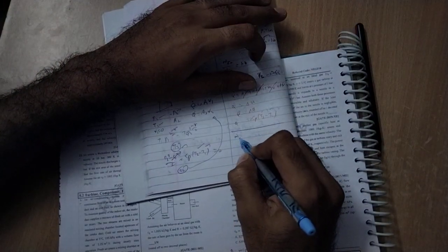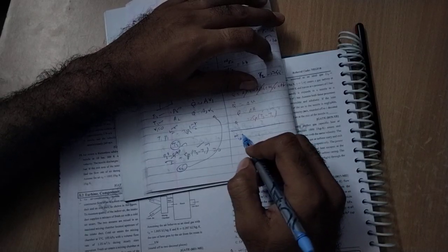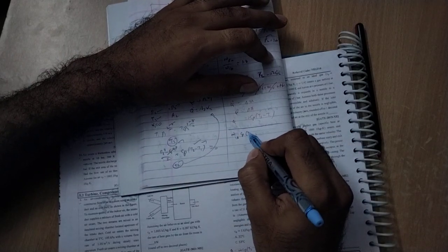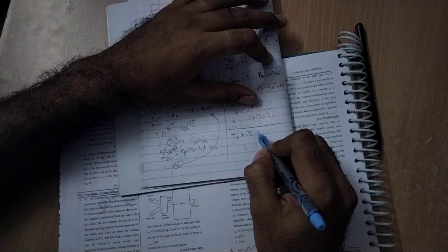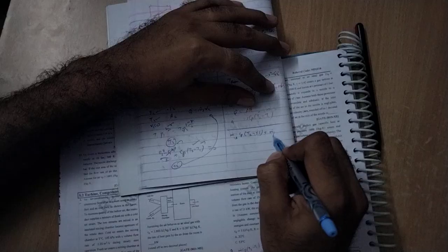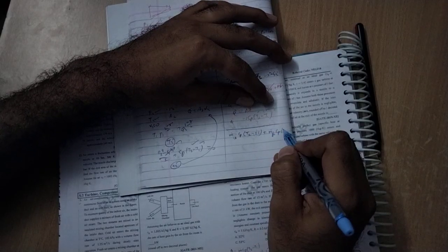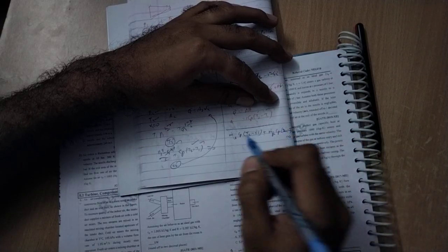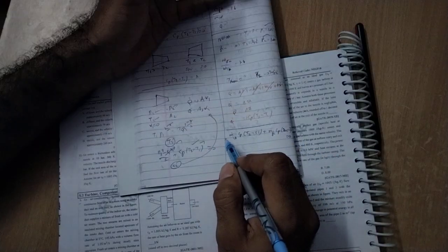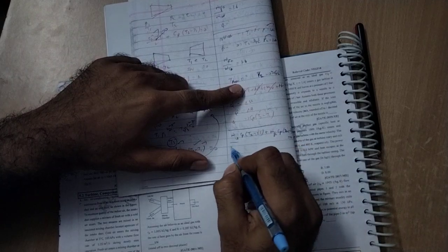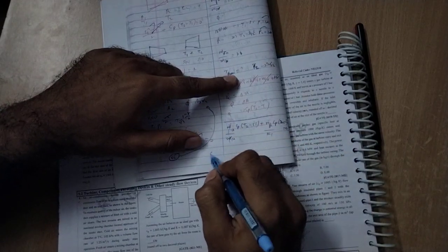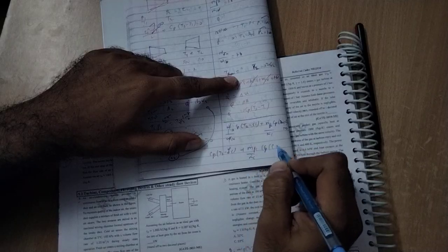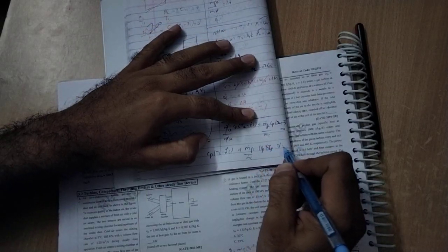So basic thing: m dot of cold air times Cp times T2 minus T1, where T1 is 5 degrees Celsius, converted to Kelvin, plus m dot of fresh air times Cp times, since its temperature will decrease, 34 degrees Celsius minus T2, equals 0. The entire equation is divided by m dot of cold air and Cp, so this cancels: T2 minus 5 degrees Celsius plus m dot fresh over m dot cold, times 34 degrees Celsius minus T2, equals 0.